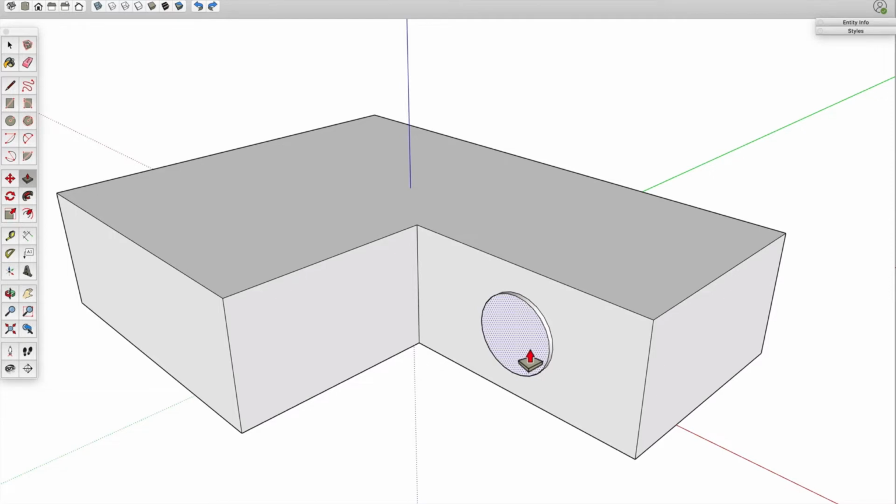So instead, what's something we can infer? Well, how about just the face that we're going to? So move your cursor on the face that you're trying to infer, and go ahead and click on it. Now you know that you've finished a push-pull where this is perfectly flat back on the surface that it came from. So we can push-pull this cylindrical surface out. We can push-pull it back flat.